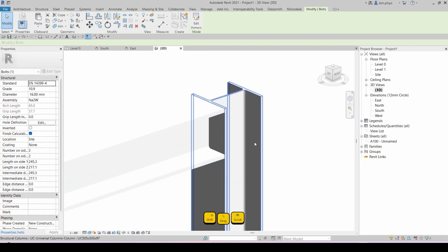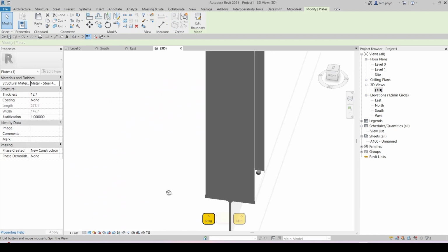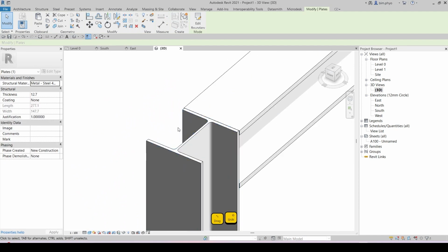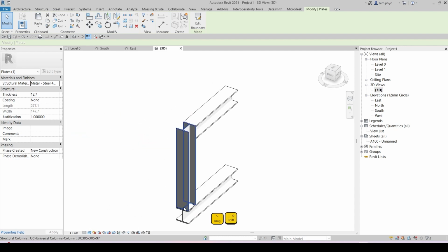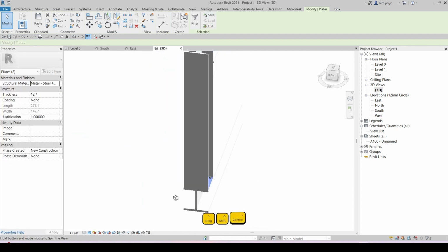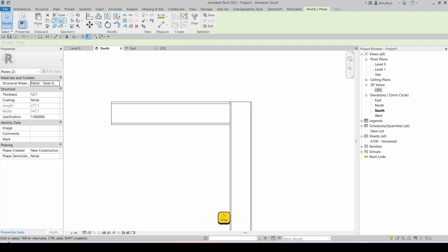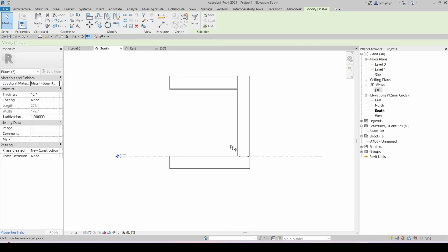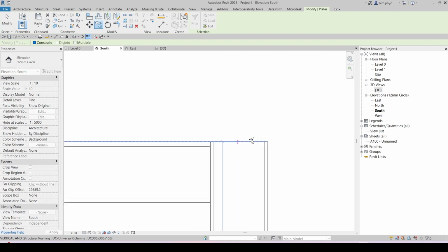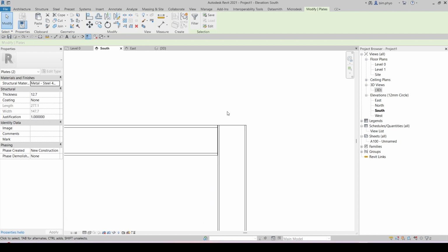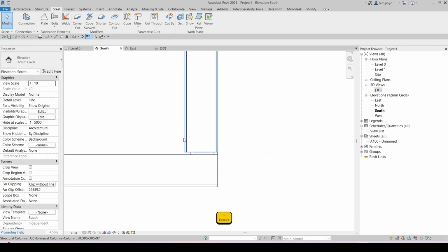So how about this? So I might need that one. Okay, one more thing. In this plate we have, I might need to close in the top view. It doesn't look good to see there is an opening, so I just want to close in the column. Then I just go into the top view, copy it here, copy it, and place it on the top. Then you can hide it, but you can't see the plate in this view.